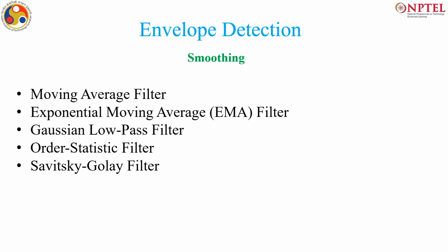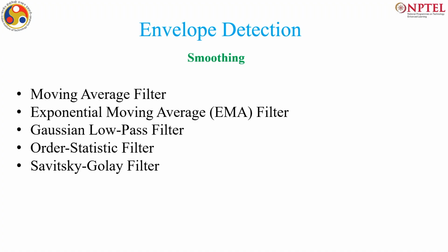So, now we have talked about the term smoothing, and this smoothing also appears as a time domain signal processing problem. So, let us try to learn some smoothing algorithms as well. Now, typically in a normal signals and systems or signal processing course, low pass filtering is termed as smoothing, but smoothing is not just a linear filtering operation. Smoothing can be done non-linearly as well.